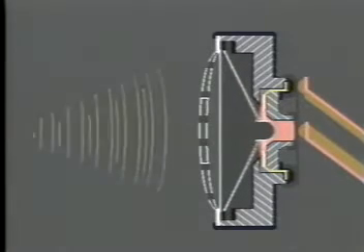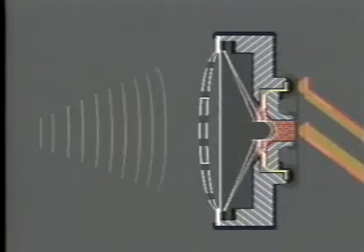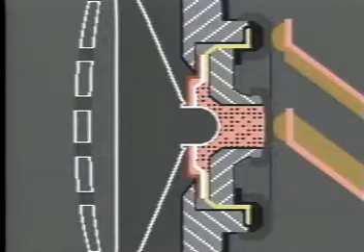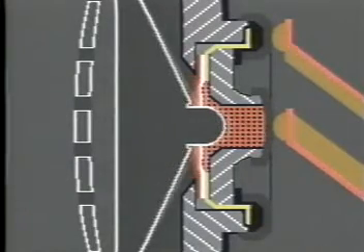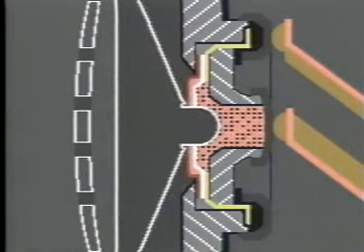In fact, it vibrates in exactly the same pattern as these sound waves. Not surprisingly, the movement of the diaphragm simultaneously varies the pressure on the carbon granules. When the diaphragm is pressed toward the carbon, the granules are compressed and the flow of current from the central office is increased. When the diaphragm is relaxed, the carbon also relaxes and the separation between the granules becomes greater.